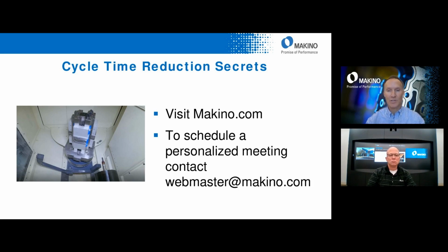Newer machines over the last several years have been with the Pro 6 control. So he's wanting to know about that. Well, talking specifically about the tap retract speed, again, that's a FANUC feature on the FANUC side of your control. As far as I can remember back to Pro 3 days, that is available standard on the FANUC side of your control. You can change that tap retract speed. So it's not specific to just Pro 5 or Pro 6.